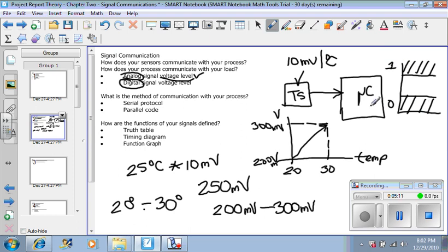If you look at the data sheet for our microcontroller, generally it's between 0 and 1 volt and between 2 and 5 volts. Which means that if we try to connect our temperature sensor directly to our microcontroller, it will only read the voltage as being 0 because it never goes above 1 volt. Of course, this is not what we want.